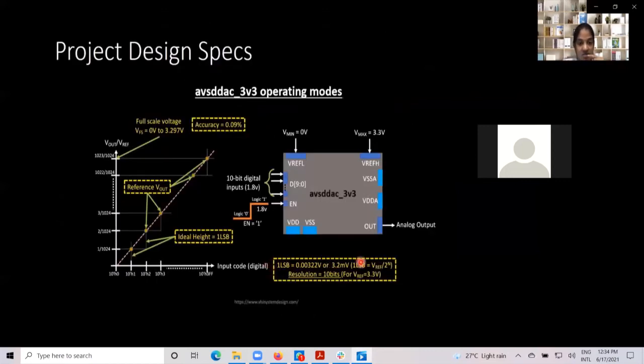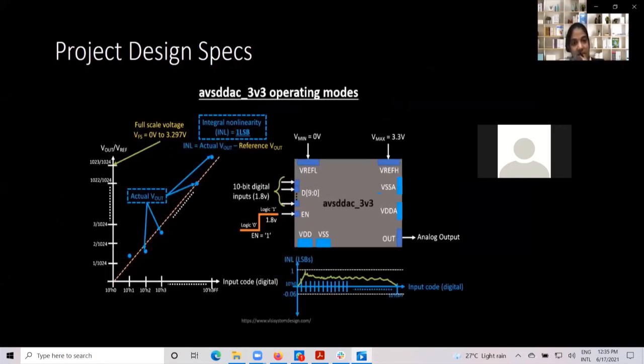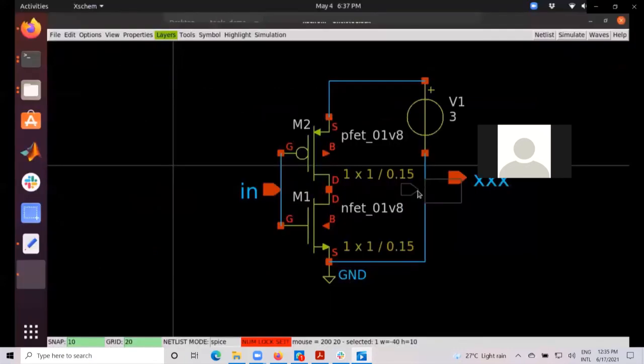And yes, now we'll look into just a quick review of the application note for this DAC. This is the first step that we do, since it's a resolution of 10-bit DAC. And this is the first step that we derive from the actual specification. INL, as we have seen, is an integration, or a sum of all the DNLs that were there till now.